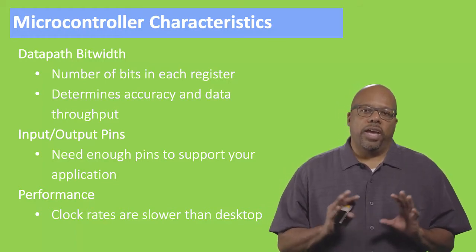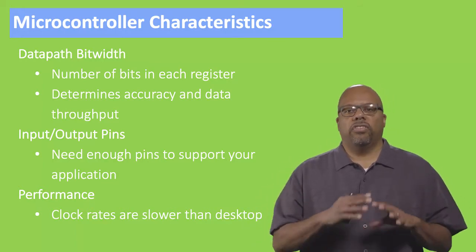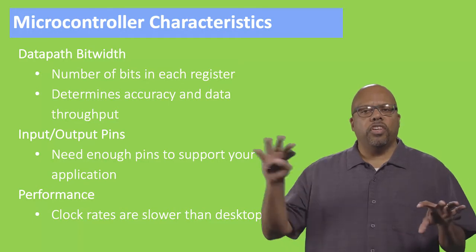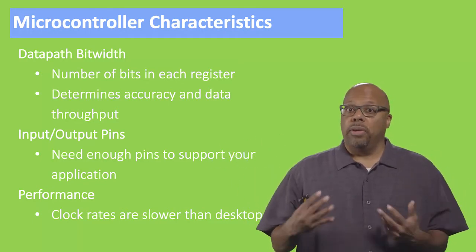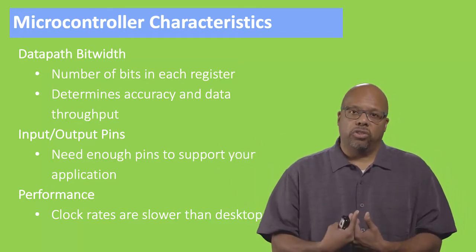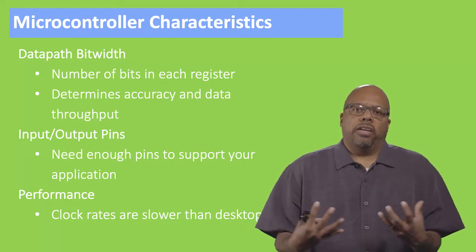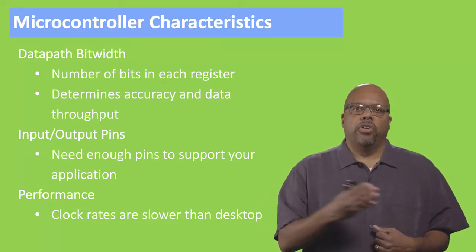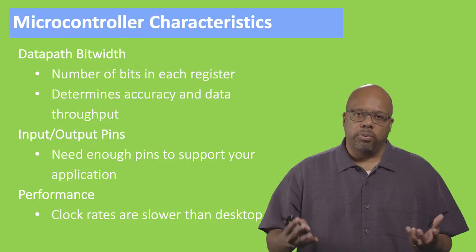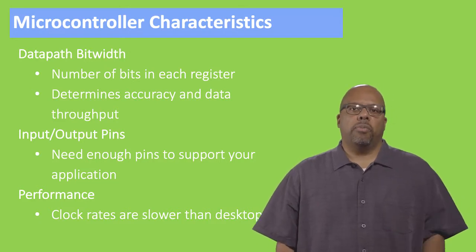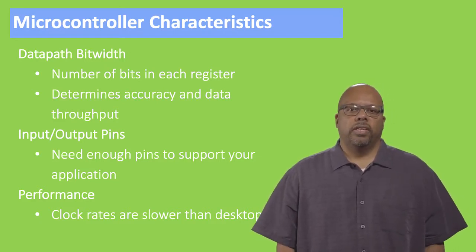So that's why very early in the design process, you have to sort of sketch out your design, figure out what the different components are you going to use, and how many pins each one of them needs to talk to the microcontroller. And so you can get a number like, say, oh, okay, I need 40 pins. And then you can find a data sheet that reports that it has at least 40 pins and so on, right? So input-output pins are important for that reason.